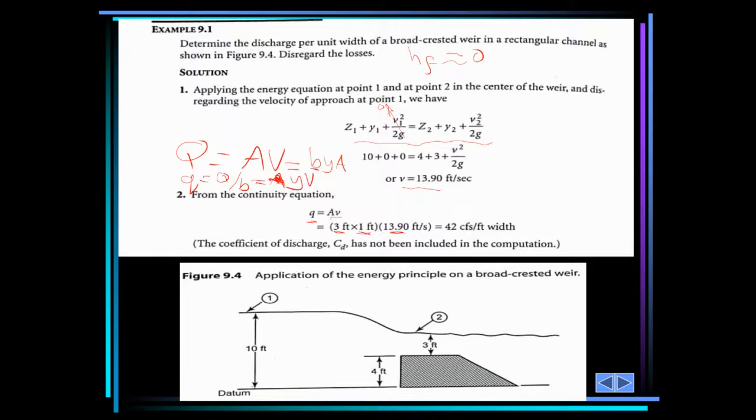The flow rate is very important, because as I highlighted earlier in chapter 1, when discussing water resources development, when planning for any water resources development, you have to analyze the need of the community, the water demand. If you remember, we talked about per capita water consumption. Given the population and their per capita water consumption, we can find the total water demand, and then we look at the available water source that can satisfy the water demand of the community.